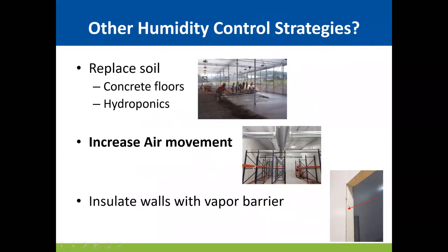What are other humidity control strategies that you can implement if that's not going to work for you? One thing you can do is, instead of having soil-based grow systems or ground cover for your floor, replace it with a concrete floor, which isn't going to evaporate water, though be careful about reflection of light.